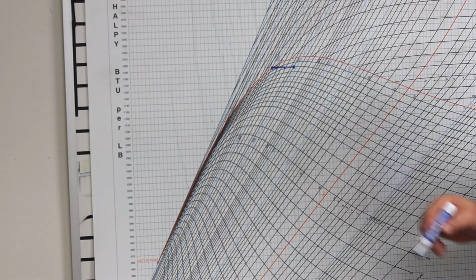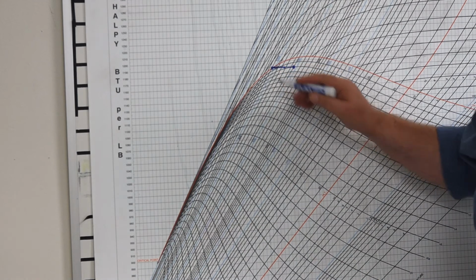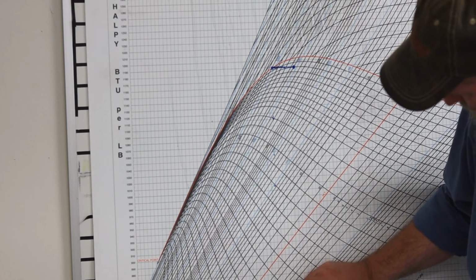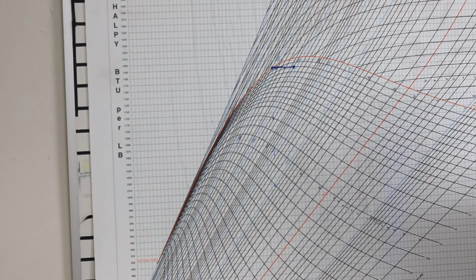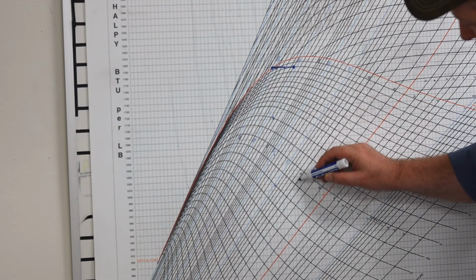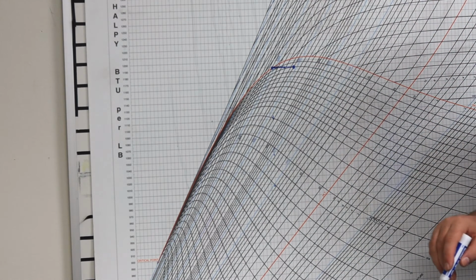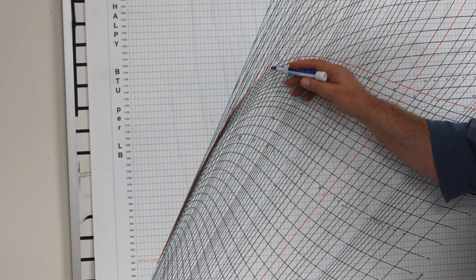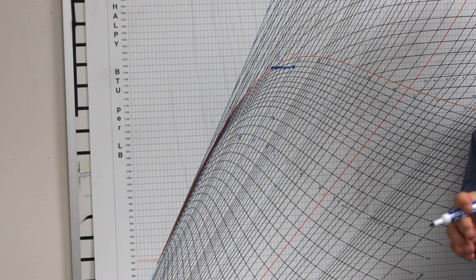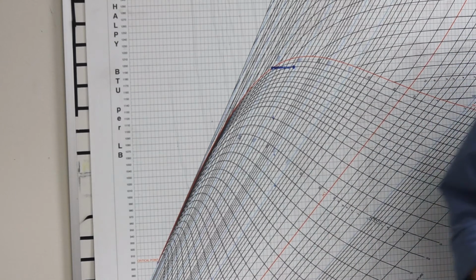So now I know what that pressure drop is. I know the change in entropy, because there's an entropy associated with this starting point of 1.38 BTUs per pound mass degree Rankine. There's an entropy associated with this final point of 1.44 BTUs per pound mass degree Rankine. So that's how much entropy was gained, how much more disorder, right? And you think about that. The steam is going through a throttling process. It's lowering pressure, it's expanding, it's becoming more disorganized, it's gaining entropy.